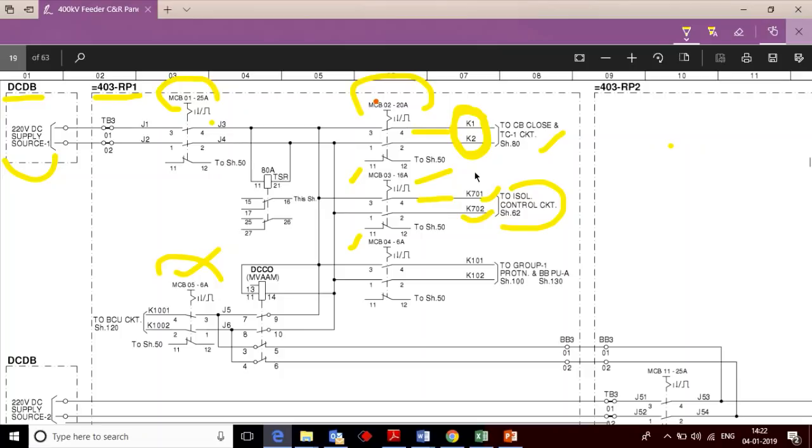Okay, next, just you understood that this circuit is divided into such parts. Now how would you find the fault? Suppose the earth fault may be anywhere, maybe in the DCDB itself. So before going to the other circuits in the switchyard, in GIS, or in the ST panel, wherever you go, first of all you have to check in the DCDB itself. Just switch off all the output MCBs of the DCDB when your system is in shutdown condition; only in that condition is it allowed to do.